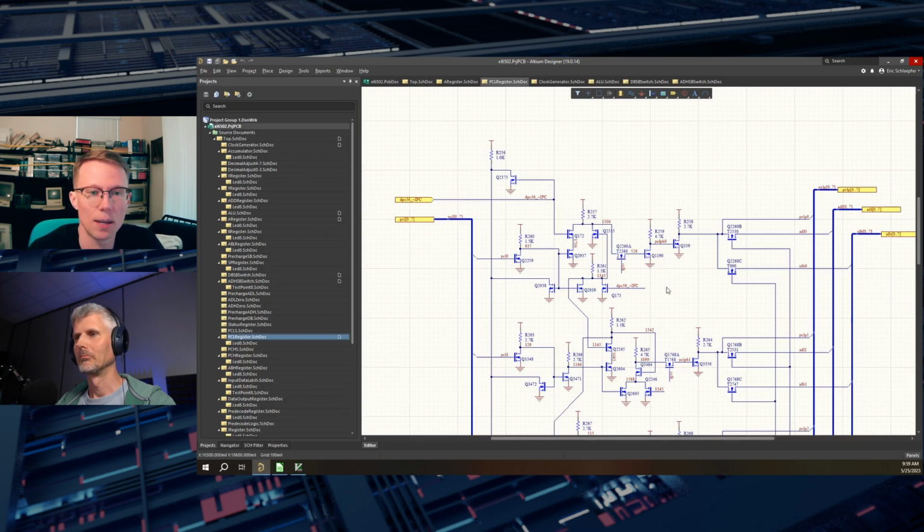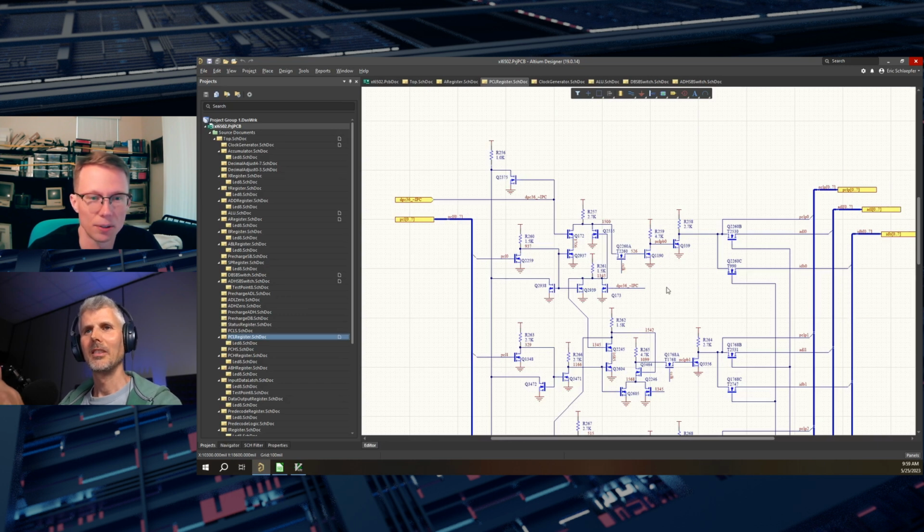And so if you think of the IV curve, you've got your classic MOSFET set of curves. Imagine shifting that to the left. And so now it's turned on essentially continuously. And so that's how you build a current source. And so that was their big innovation. And they were designing this for that process.